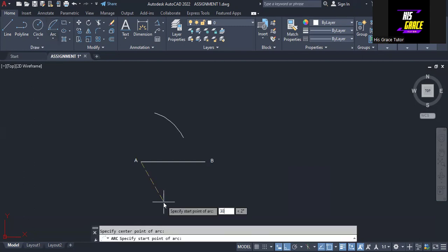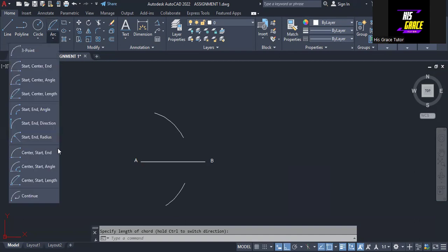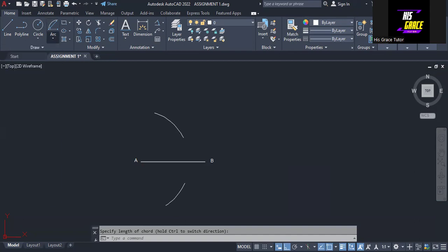The arc usually goes clockwise, just take note of the way I'm doing it again. So we take it and make use of center B here. We draw an arc, radius 30, so it goes like this, and then we repeat it again, okay? From B here, the distance is 30, so we have this.